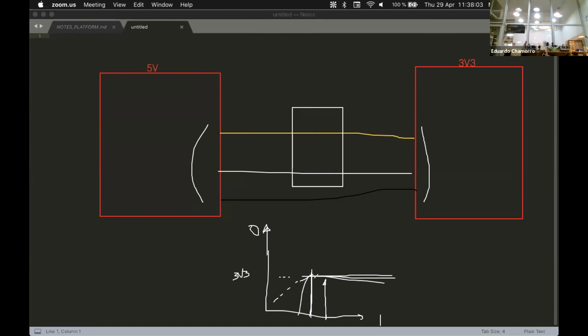Just another question. In this case, for example, the 5 is also powered separately. So in this case, there could be 2 options. And the good option here, in my opinion, is to power this with 5 volts. So this one comes with 5. Yeah. That is a 5, not a 3. And then you have the LDO. And the other one powered separately with the 5. Exactly. Because when you power the 3.3 one, it passes through the LDO and converts up to 3.3.